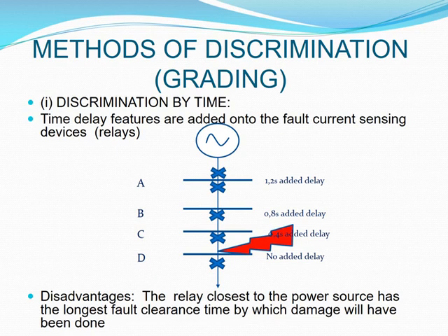Then your breaker that is just below C is set at 0.4 seconds in this case, delay time from what your breaker D is. So what it means is that if the relay at D, for whatever reason, didn't operate, maybe it's malfunctioning, then your breaker C is the one that needs to take out this fault, but it will only do so in 0.4 seconds after the time that breaker D was supposed to have taken out the fault.